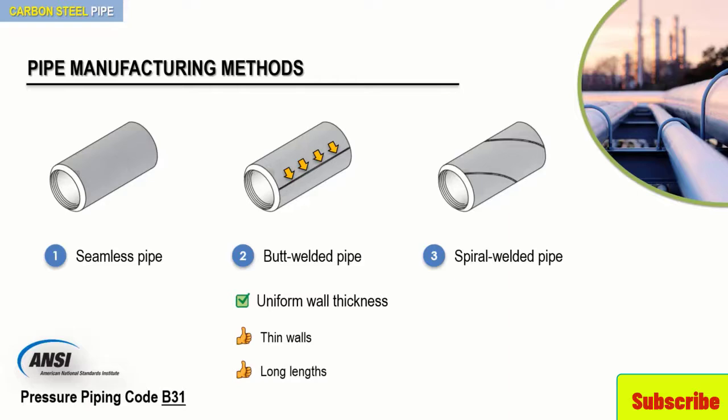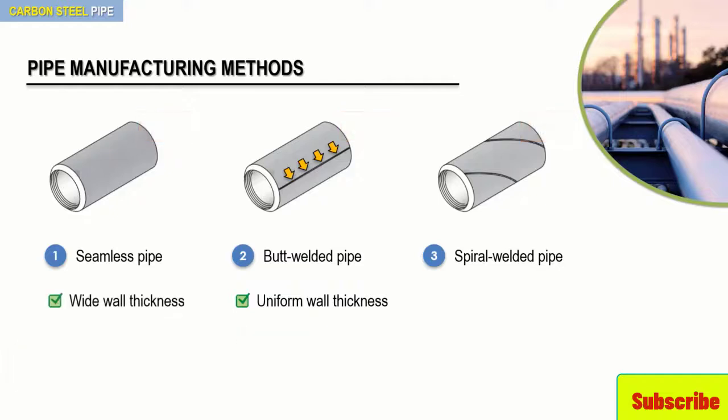This code assigns a strength factor of 85% for rolled pipe, 60% for spiral welded pipe, and 100% efficiency for seamless pipe. So, clearly here, seamless pipes are more robust than the others, and therefore will withstand higher temperature and pressure conditions. Also, in general, wider wall thicknesses are produced by the seamless method. However, keep in mind, for the many low-pressure uses of pipe, the continuous welded method is the most economical.